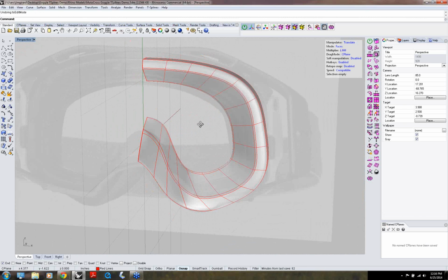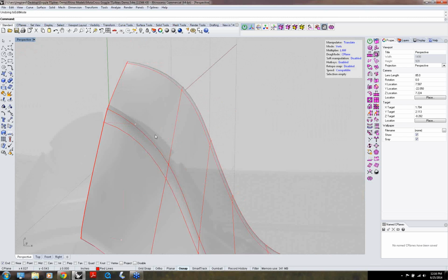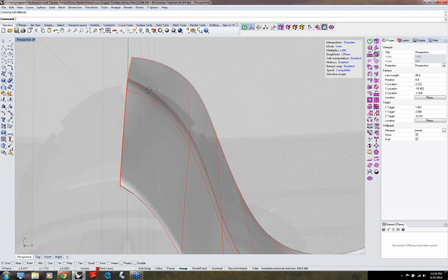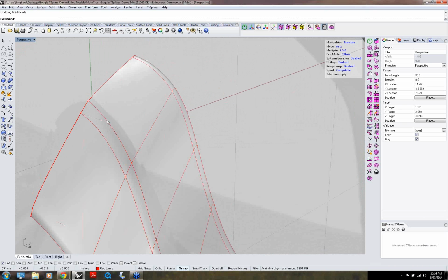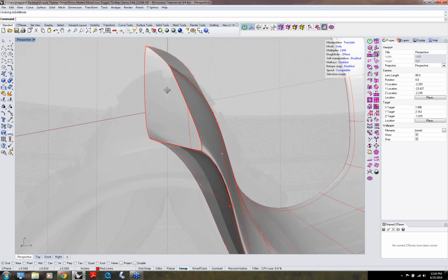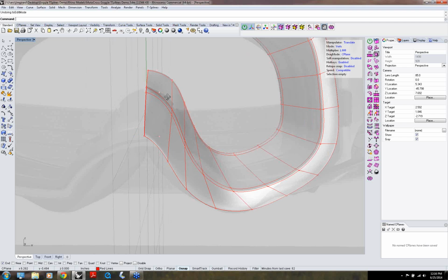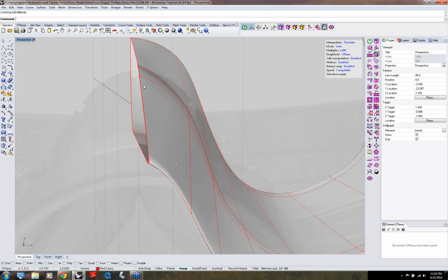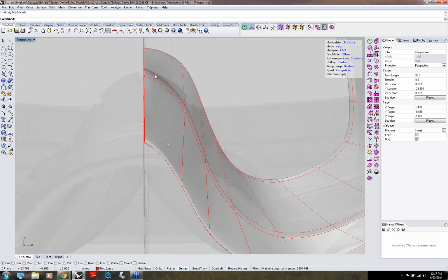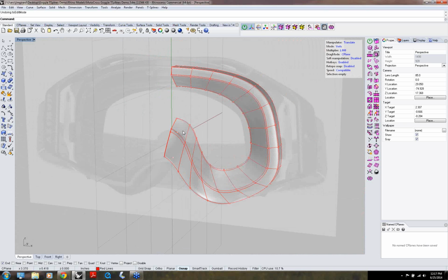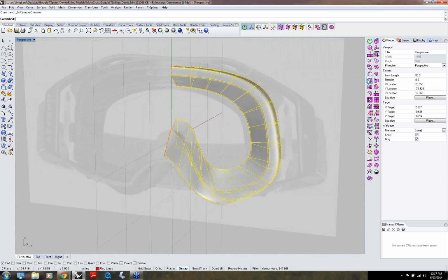Now, one of the other issues about T-splines, if you'll notice, we have these things called tangencies. And there seems to be some strangeness right here where that tangency is off. And that is because when I welded this line together, this one kept its tangency with that point, and the rest of them aren't. And it took me a long while to figure this out, but if I select all my points and I hit this key, which I'll sort of highlight, it's called crease edges. If you hit remove creases, it resets the tangencies to the normal, to the points.